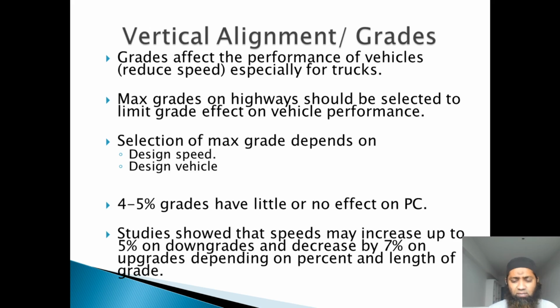You must have seen at some places that trucks normally carry huge loads. So if we don't provide proper alignment or proper grades, it will be very difficult for trucks to overcome those slopes. Maximum grades on highways should be selected to limit the grade effect on vehicle performance. Now what will happen if we give very steep grades? That will affect the performance of the vehicle. So it should be designed very properly.